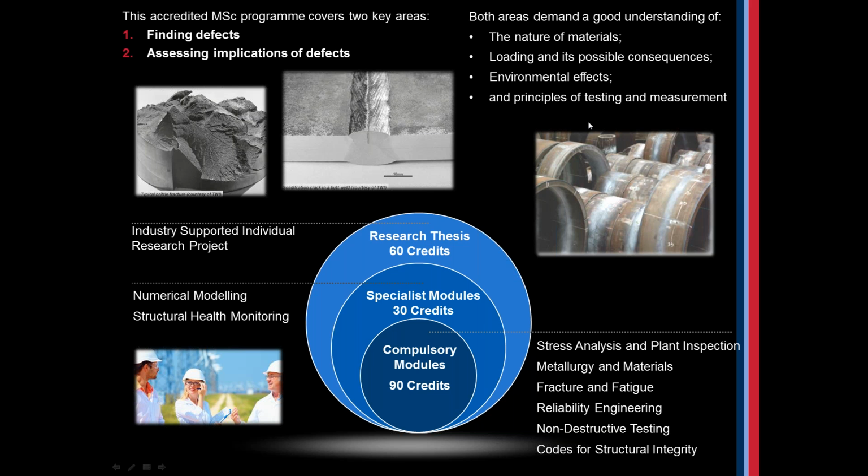Understanding the environmental effects on the structure. For example, if it's going through a very high heating and cooling cycle, this can generate quite significant thermal stresses, and ultimately this could result in accelerated fatigue of your particular component. So trying to understand how the environmental effects can also affect the load carrying capability of the structure is important.